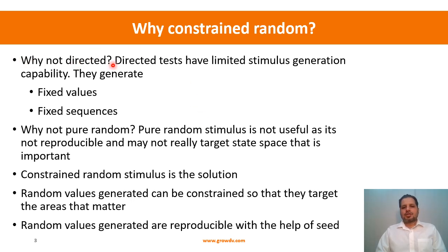The first question that we need to ask ourselves is, why not just rely on directed test cases, right? So what does a directed test case mean? Why we need to understand this in a little bit of detail is so that we can flip the script. That is the idea. In a directed test case, there are two things that remain fixed. One is the sequence of operations that you create, plus in each of those operations you use certain variables.